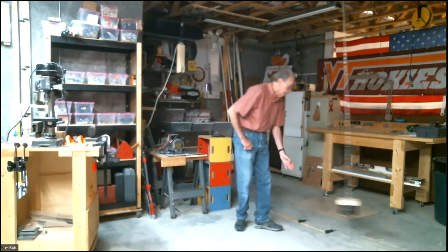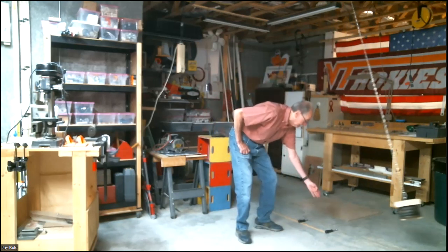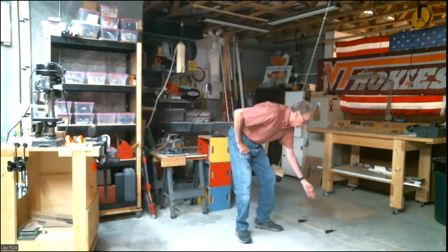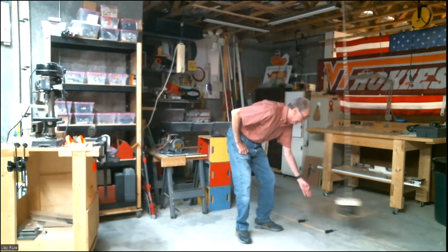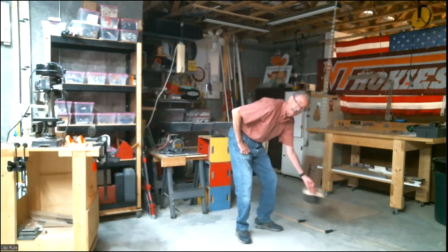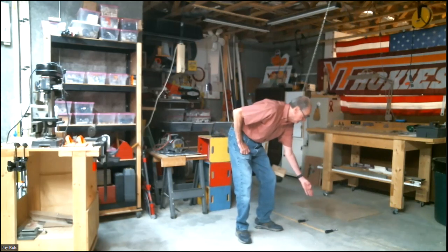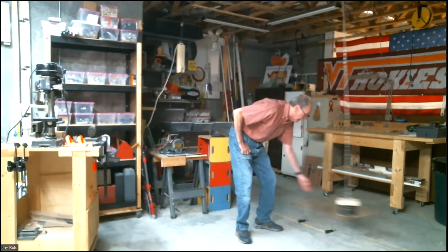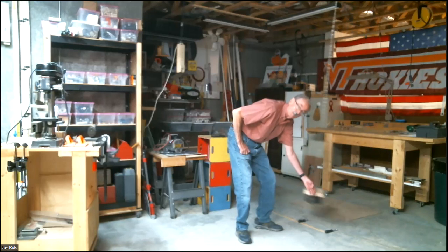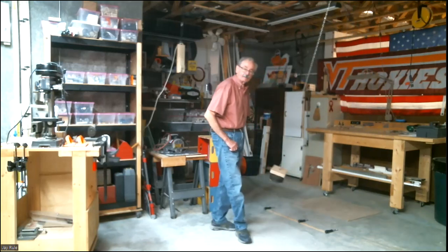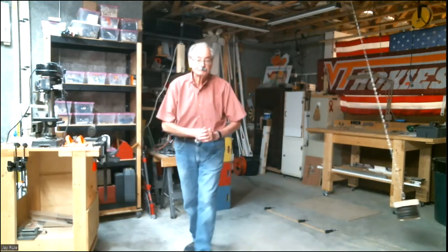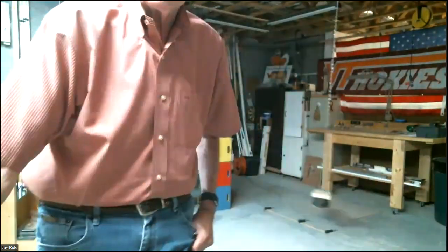So how about this middle point here? Well, we're going to say that the potential energy here, we'll set the datum as the center line, the center of gravity of the mass. So the potential energy here is going to be 0, but this is where we're going to have the maximum velocity. So the kinetic energy at this minimum point is going to be the maximum kinetic energy. Okay, so you're getting the idea. All right, let's go back to the slides.